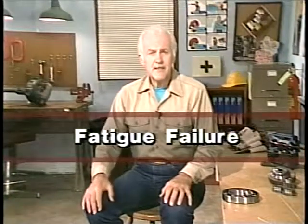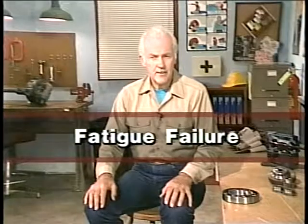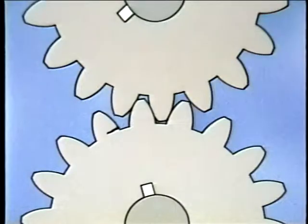One type of gear problem is gear tooth breakage. There are several ways in which a gear tooth or teeth can be broken. One way is through fatigue failure. Fatigue failure usually results from repeated bending or flexing of the gear teeth. Let's look at an illustration to see what can happen. The process of fatigue failure will be accelerated if some defect was present when the gear was manufactured, such as a tiny crack in the gear material.